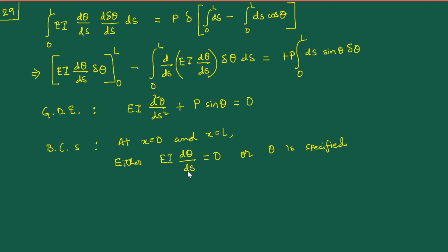So there is your hint. Think about what this d theta/ds, the curvature, would be in terms of R, the radius of curvature, and then see what that EI divided by the radius of curvature denotes. I've almost given you the answer, but you think about it anyway.